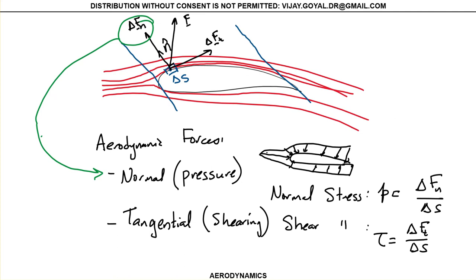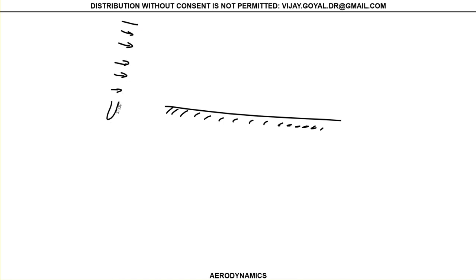So with these ideas fixed, I want to talk a little bit about the shear stress because it is important to understand what it's doing. Just imagine you have a flat surface, and the surface is fixed, and you have a stream coming at a velocity, let's say U. What's going to happen here is it's going to create a gradient that's going to look something like this.